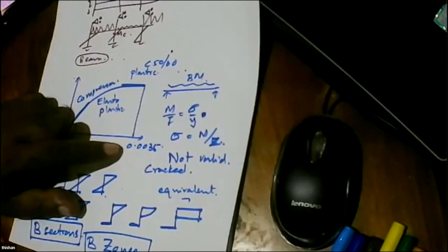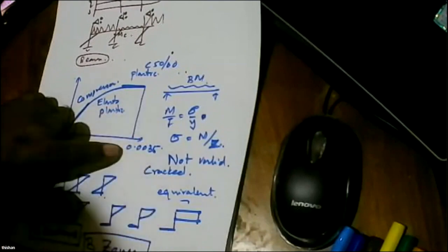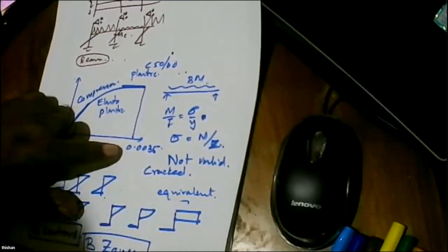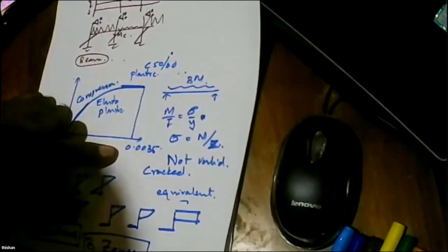But theory is theory. But people did not know about this theory called D-zone. So they said, okay, strut and tie. Because the test results do not comply with the beam theory. They give different results. So they came up with strut and tie, which gives a better result. But they were not explicitly telling us. They said, okay, if it's a pile cap, you must use the strut and tie method. If it's a corbel, you must use the strut and tie method. So they were giving the solution, but not explaining the problem adequately.